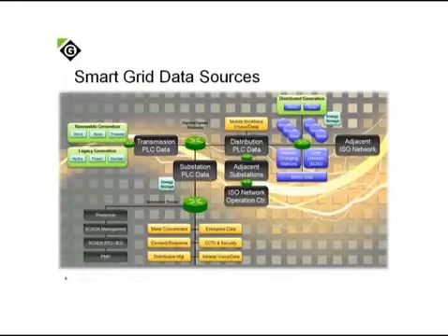So as we move over to more of an IP-based network, we're seeing that your operational data, your production, or your protection, your SCADA management, a lot of the RTU, IED type information, PMU type data information, is increasingly becoming packetized and being fed into a substation router, which is then fed up and either shared with other substations or sent into the actual network operations center for management and control.